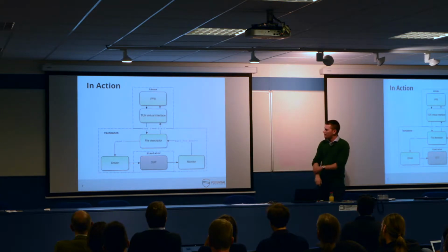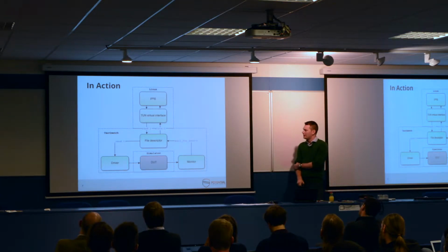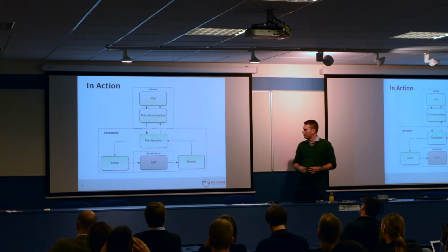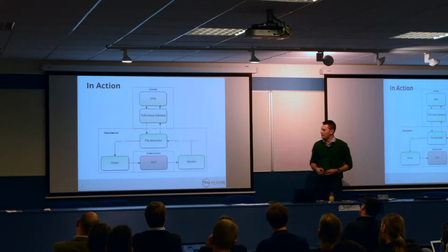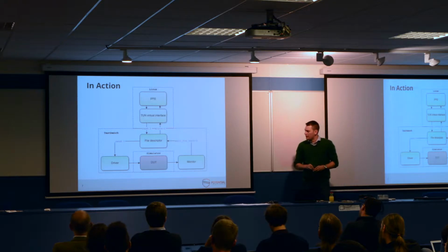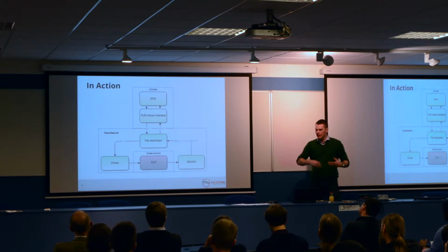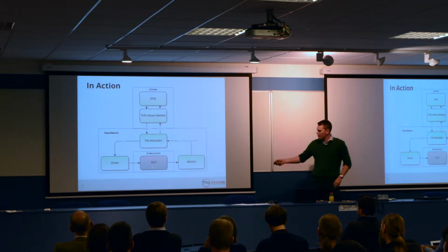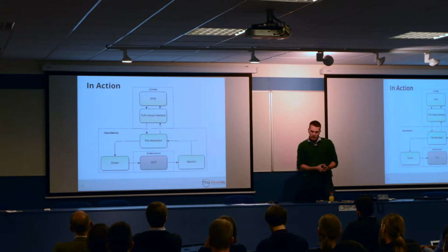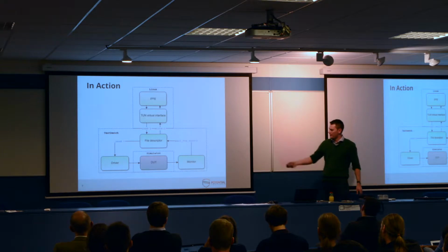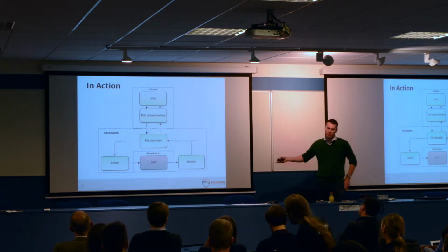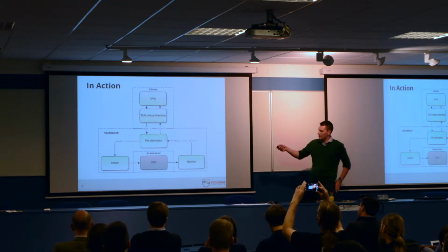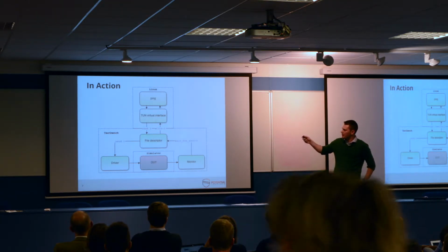Okay, so if we take a look at an example, this is something that might be considered slightly difficult to do if you were just limiting yourself to VHDL or SystemVerilog. And this is the kind of area where being in Python really shines. Let's say we've got some design which is responding to Ethernet packets, so it's like an ICMP stack that's going to respond to pings. And we want to use the Linux command line ping utility to ping our design running in simulation.